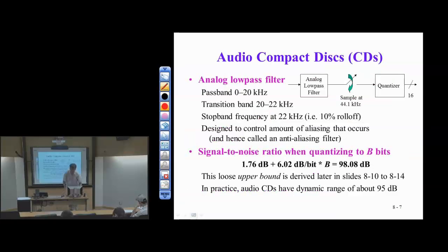Now in lab, it's mostly C code and it's whatever the compiler does, but you should be aware of what's going on. And we're in floating point in lab, so this is not really an issue for us. Right? We just scale the floating point value as we need to. But if we go to a fixed point implementation, then you have to start worrying about these issues.